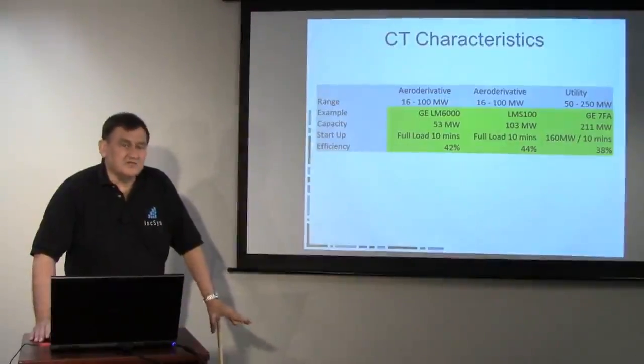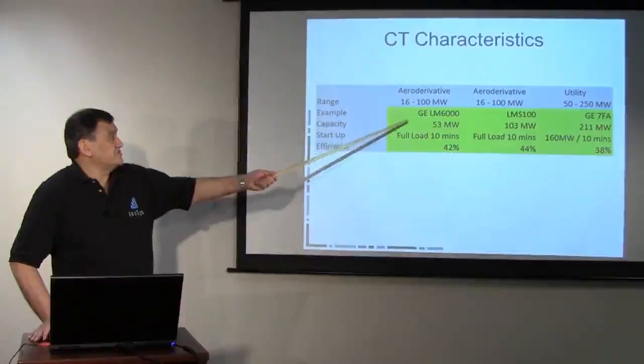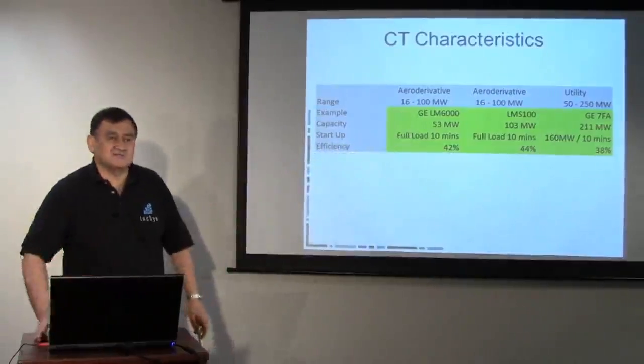As we will get into in the balancing module, there's a NERC criteria called the disturbance control standard. After there's been a loss of a unit, you have 15 minutes to get the ACE back to where it was before you had the loss of that unit. And so these types of gas turbines are an excellent solution, where you can actually start them up from cold and get them online within that 15-minute period.